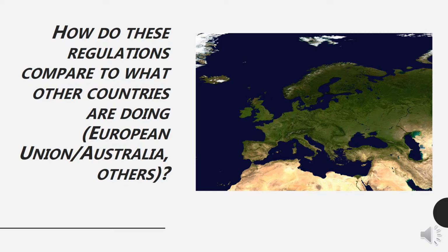Among the data available for global DBP regulations, Australia is an outlier in that its regulations allow much higher levels of trihalomethanes, 3 haloacetic acid species, bromate, and chlorite. Finally, the World Health Organization has set regulations on individual trihalomethanes,